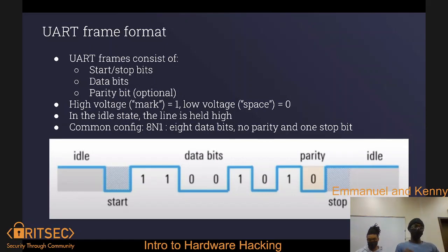The more you send data, it'll go up and down. When it's lower, it means it's in the low voltage, which you know as 0. So 1 and 0. Can I touch on this real quick? Yes. But going back to the baud rates, right? This is a waveform, and it generally fluctuates from high and low based off of a clock, and the clock will generally be above this, right? If one device is, let's say, at 4800, and another device is reading at 1,000, my bad, I can't count, these changes and fluctuations will be completely unaligned. So baud rate's important.